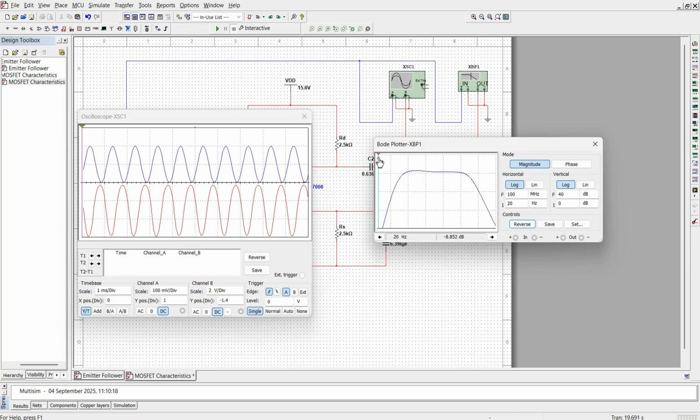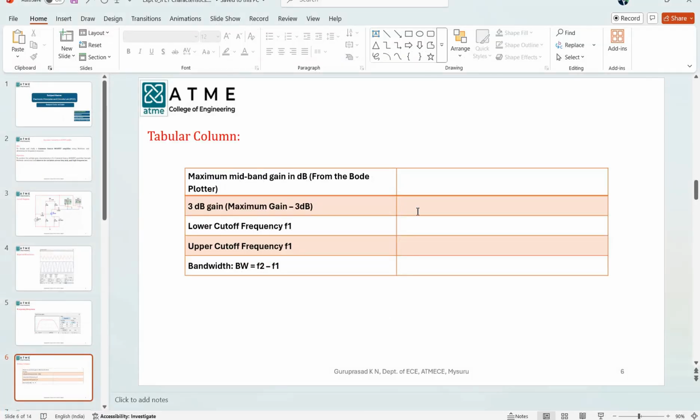Now, let me find out. As an example, see here at 230 Hertz, the gain is 27.72 dB. Similarly, at 429 Hertz, the gain is 28.656 dB. Now let me check what is the maximum value of gain. So the maximum gain is here 31 dB. So this should be noted in the graph. So the maximum gain is 31 dB.